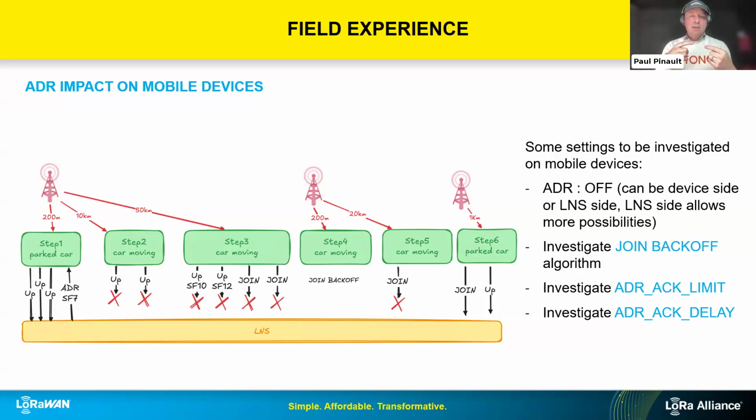What I mean is that the ADR always returns to the device to keep the same data rate, which basically means do nothing with the ADR on the device. So you can keep ADR active on the device for future usage, but not use it in that situation. All right, thank you, Paul.